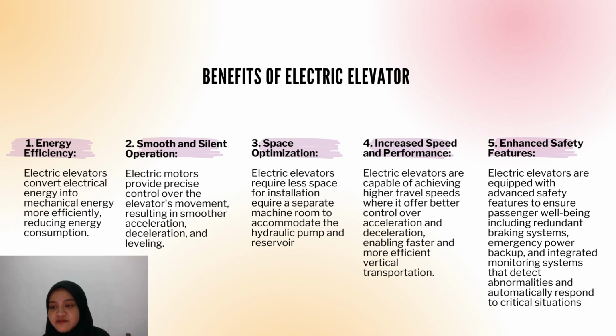And the third benefit of this type of elevator is space optimization, where it requires less space for installation, because hydraulic elevators typically require a separate machine room to accommodate the hydraulic pump and reservoir. Whereas electric elevators can have a compact machine room or even be machine room-less designs. The space-saving advantages of electric MRL elevators allow for more efficient utilization of building space.